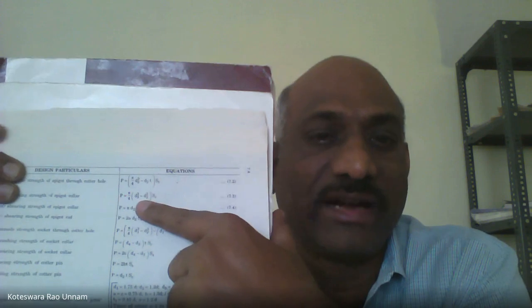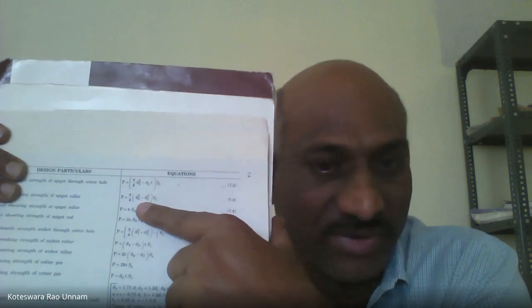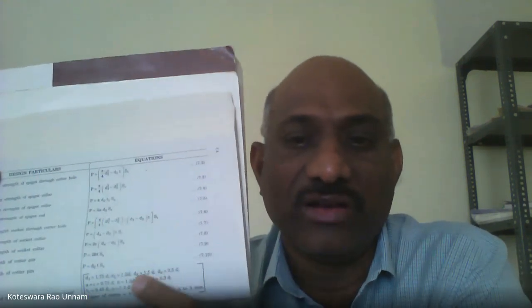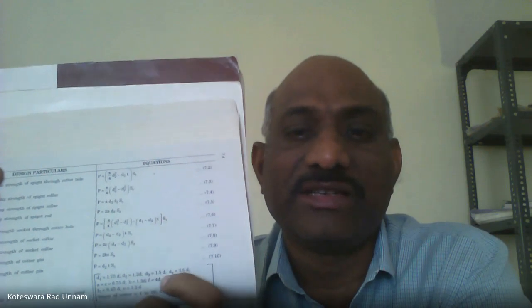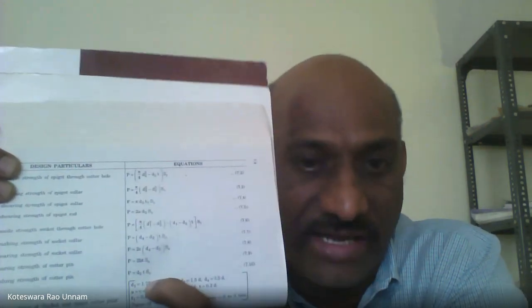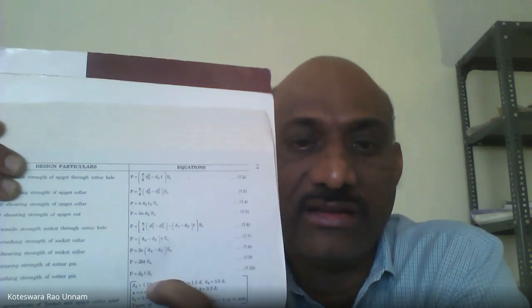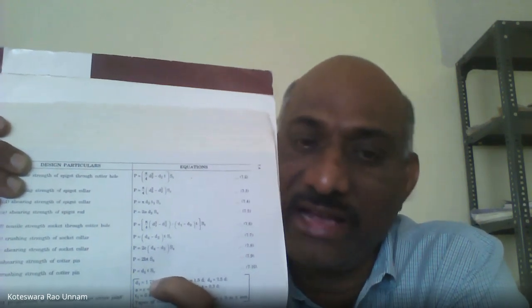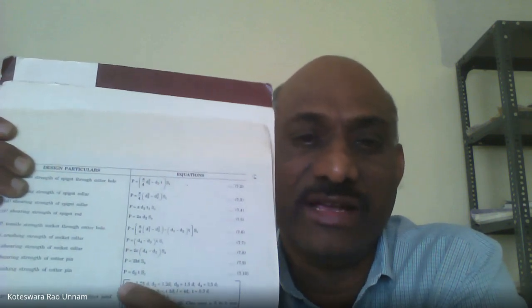Let us say first I find out D1. Let us say I got D1 as 40 or 50 mm. Now if I go to the empirical relations, you have an empirical relation for D1: D1 is 1.75 D. So before that, I need to calculate D also. Now I have D and D1, so I'll check whether D1 and D are related like this.